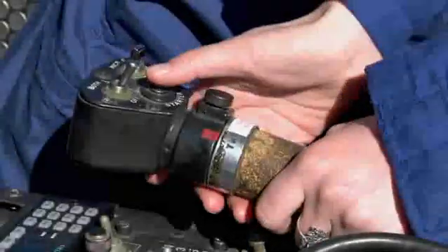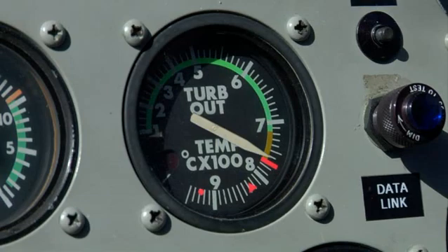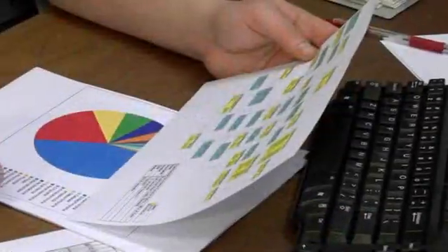What if you had seen that your pilot had recorded 3 near misses with a hot start last month? It didn't hit 1,000 degrees, but it stayed over 800 degrees for a while. If you didn't write that down and you didn't know that it was happening, you wouldn't be able to make the assumption that if this is happening 3 or 4 times and almost getting to the accident level, sooner or later, somebody's going to have an accident. That's the value of reporting hazards and occurrences.